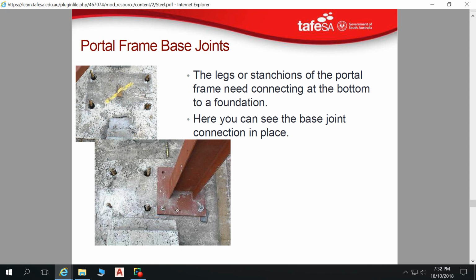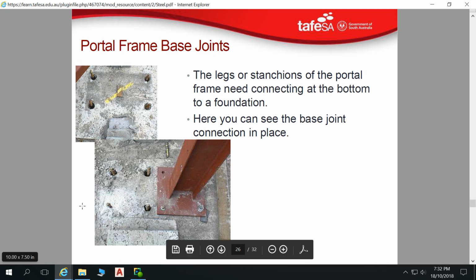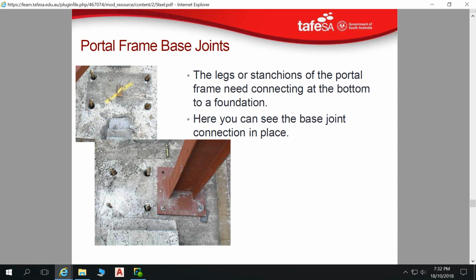I can't even think where I'd begin to deal with that, actually, because obviously your footings would have been designed to take load over this section here. To then place the load eccentric to where the footings were designed to take that load, you've got issues there. But also, you've got your fixings which are cast in threaded rods.